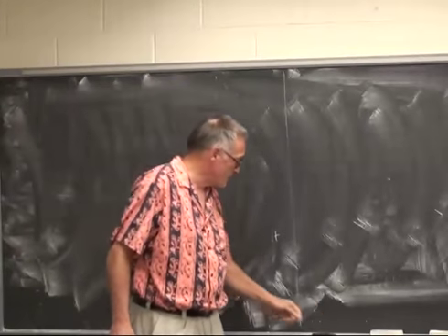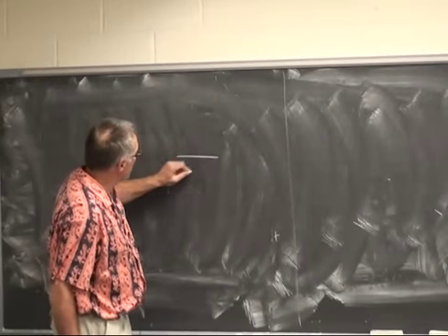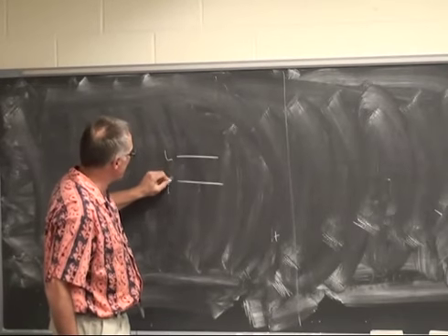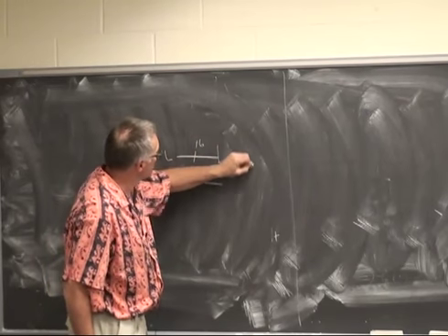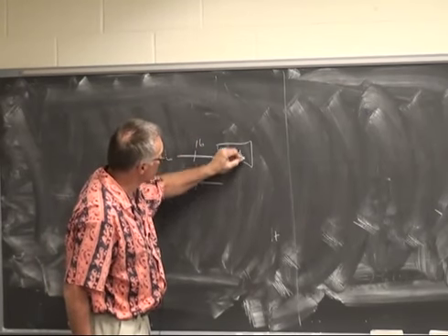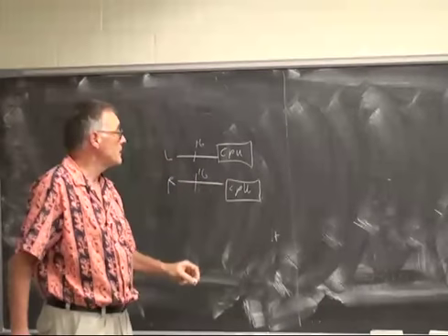The audio codec produces 16 bits of 2's complement input. So you're going to have two channels, left and right, of 16-bit 2's complement. Each one of these is going to go into its own CPU because you're going to instantiate two of them.